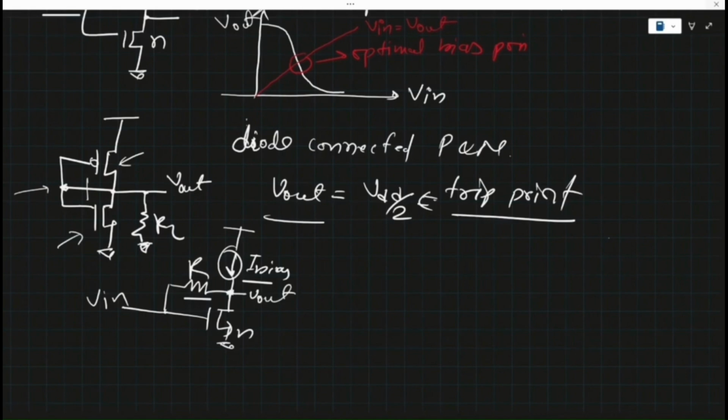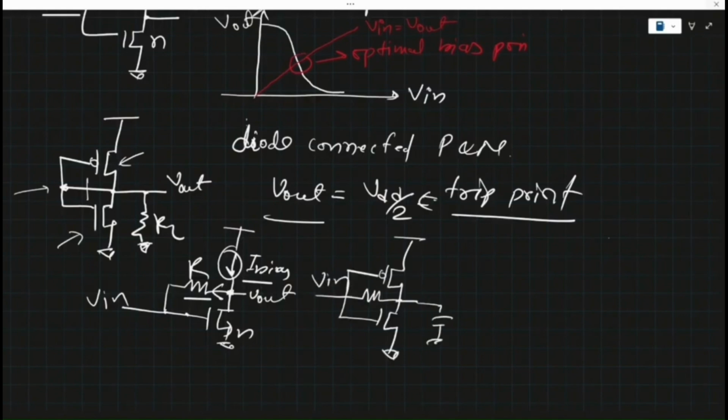Similarly, the same thing we can do over here as well. We have this inverter, then we can connect one feedback resistance, and here we have the input. Another way of looking at this circuit is to assume that this inverter works as an amplifier. How does that amplifier look? Let's say this is minus A, the gain of the amplifier.